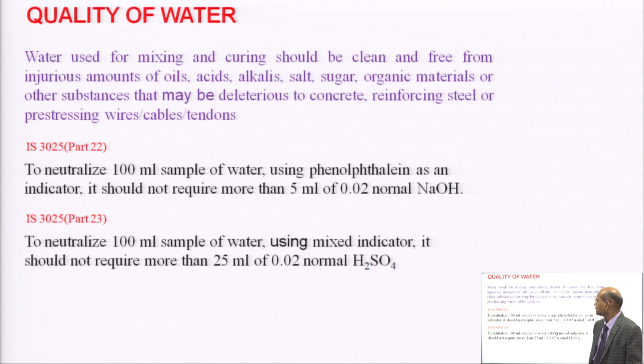Because what will happen if the quality of water is not good? If you are using water which is not qualifying, that is going to reduce the strength of the concrete, and not only reducing, it has a long term effect.